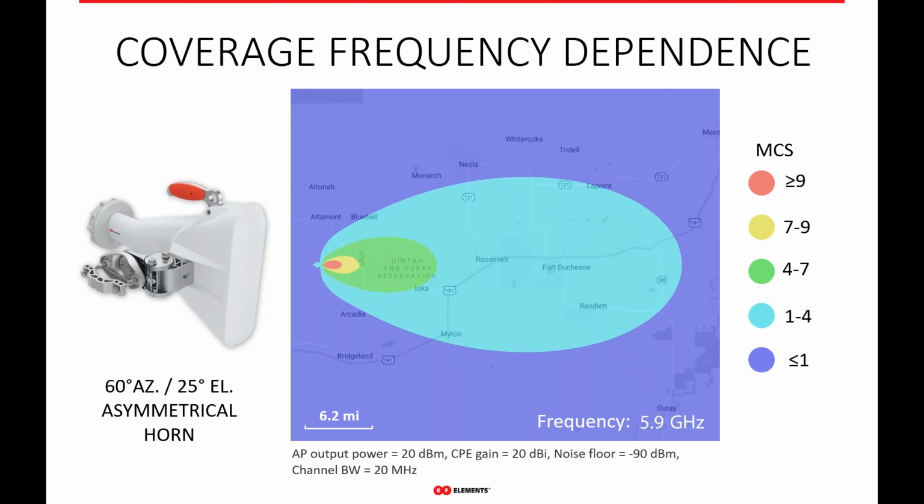Even more, right, you see this with our horn antenna. So, if our patch array sector was stable, then horns are really super stable, basically. So within the spectrum, the coverage is virtually unchanged, right? Which is what you really want from any sector or directional antenna. This is the way you can really rely on its performance and provide a kind of headache-free service for your customers.